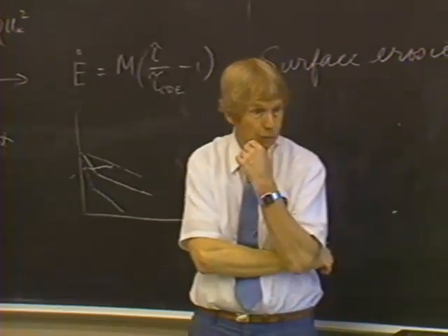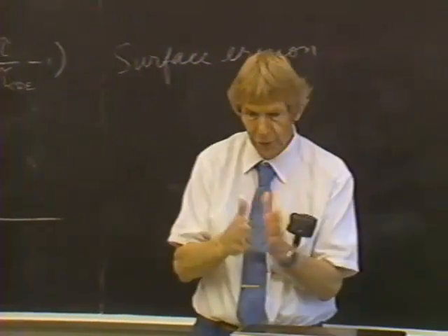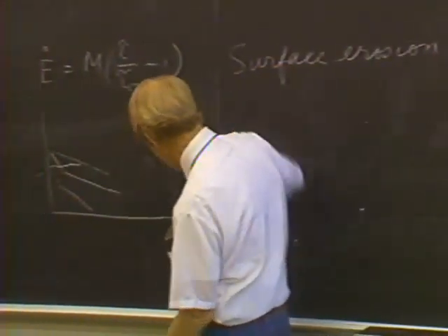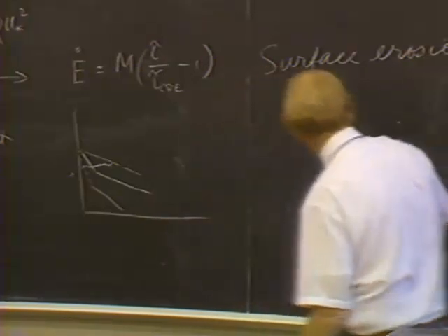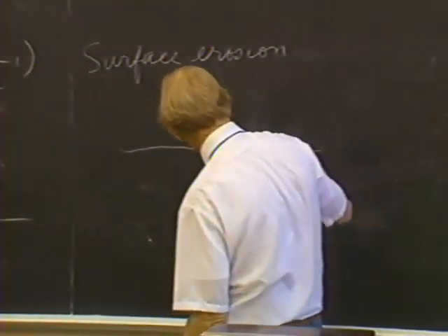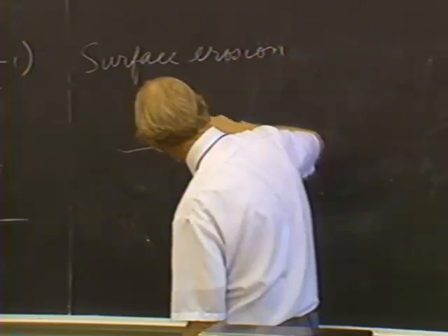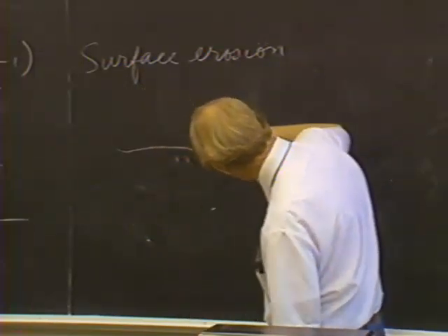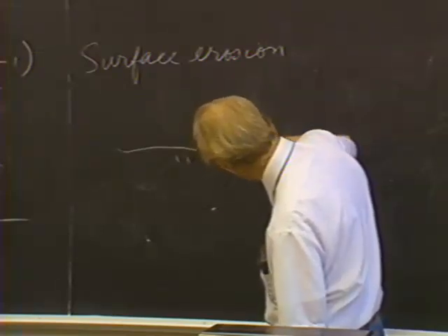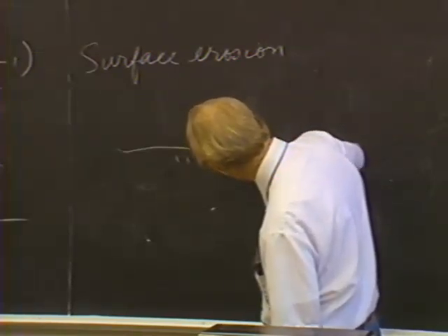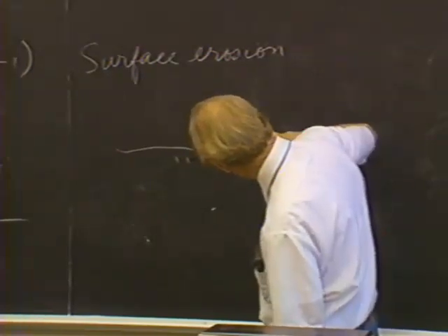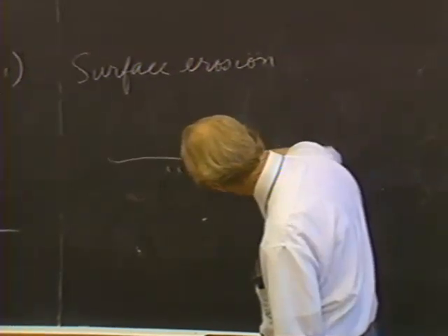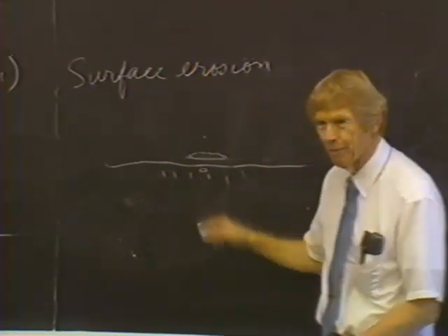That process is bulk erosion. What happens is that the material is viscoelastic and it deforms under the wave. As the bed moves, say this is the bed, as the shear stress on the top goes back and forth, what you see is that the bed itself goes back and forth. In fact, this won't be just back and forth; as the bed yields, it'll be something like this. And the bed will form a smaller one, something like that.